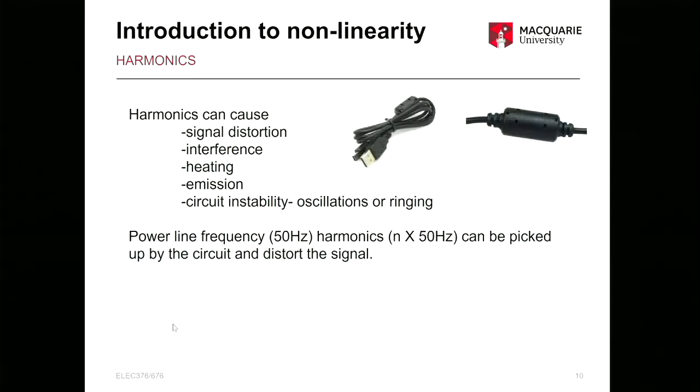You must have seen these ferrite beads in your laptop chargers and maybe phone chargers and several electronics. In this context, you can say, yes, they are there to prevent those harmonics from coming in and also prevent harmonics generated by your equipment from reaching outside or going into the power lines.